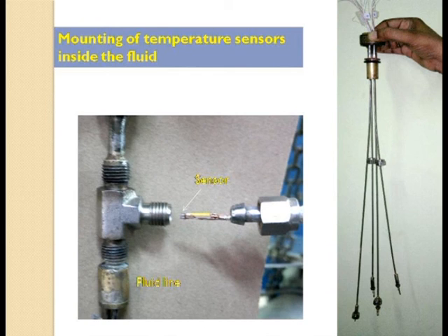Okay, so this is the sensor, and this sensor is to be placed inside, and fluid will be passing through this, so that after putting this one, this will be sealing the gases. Gas will not come out through this, because vacuum is here. You have the vacuum outside. So this nut is tightened across these threads, and this sensor is there, and there is a hole inside this nozzle, and all wires are going through these holes, and they are connected with a capillary tube.